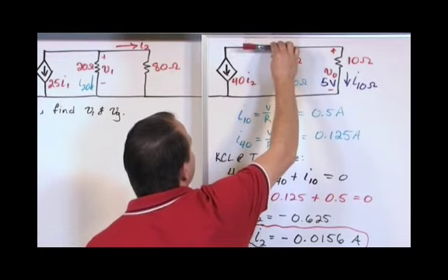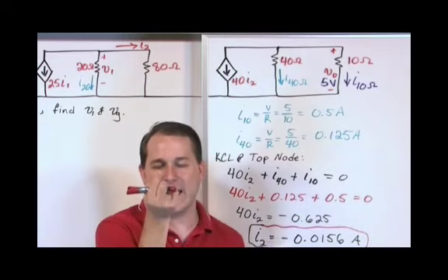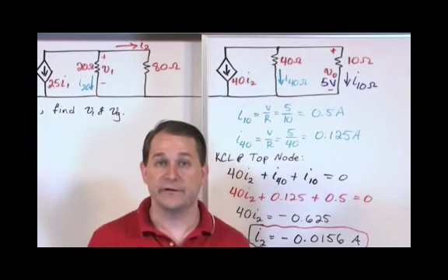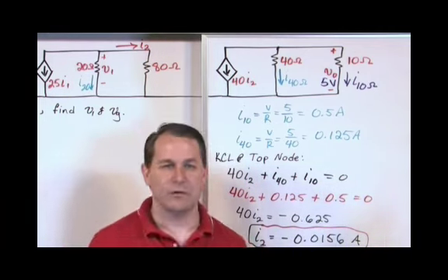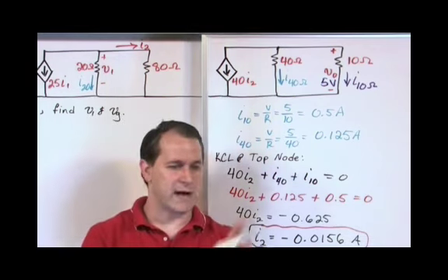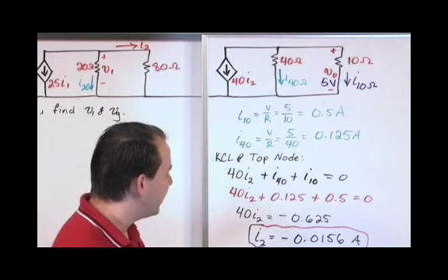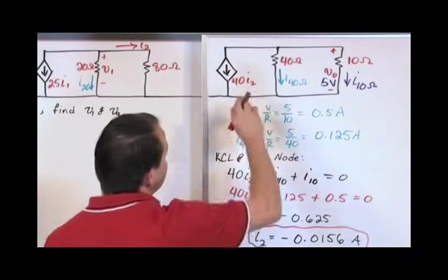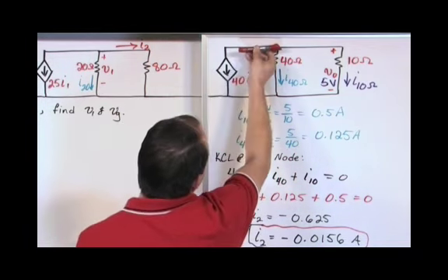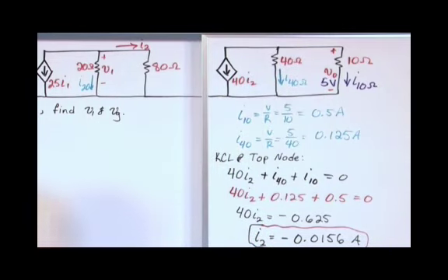it would mean that you would have all three currents going out away from this node, and that's physically impossible. You can't have current sourcing out of just a node intersection. Kirchhoff's current law says whatever current comes in must come out. And you can't have a situation where you have current flying out three different directions with no input current. So what this is all really saying from a sanity point of view is I sub 2 is backwards, which really means this is backwards, which really means if we really built this thing, the current's flowing up into this node and then of course branching off. That's what it really means. So always do a sanity check on what you get. So now we know what I sub 2 is.